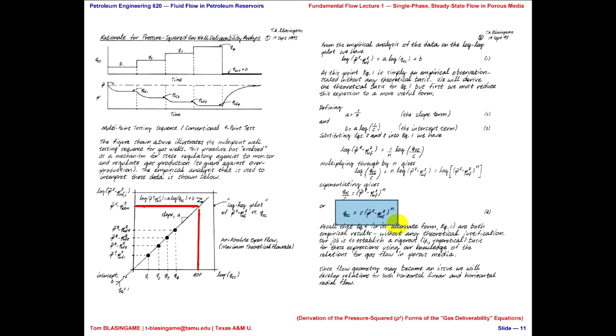In the steady-state case, the external pressure is fixed. In this case, we cannot refer to the external pressure because we don't know what it is. We refer to the average reservoir pressure. Subtle difference, but also very important. So we have to actually use average reservoir pressure. That's one difference. What's the other? Here we can have the n value be anything. For the steady state case, when we derived it, the n value has to be 1. Okay? Now, why is all this so important? Again, it's sort of the building block equation for rate predictability and so forth.